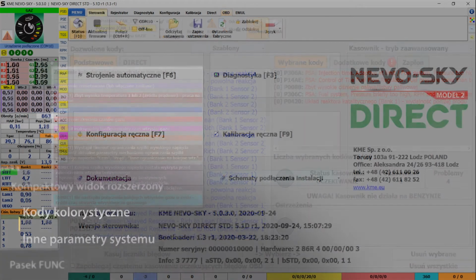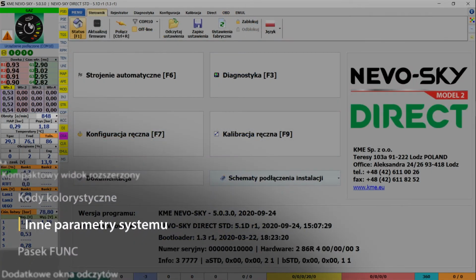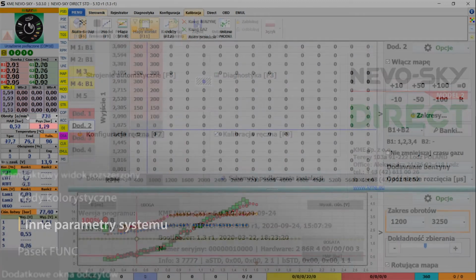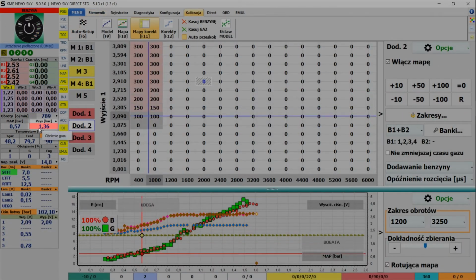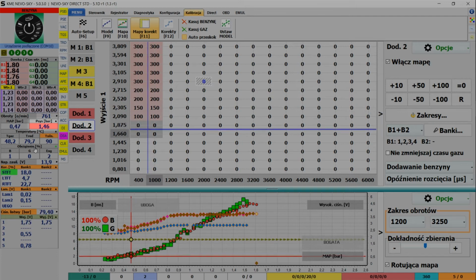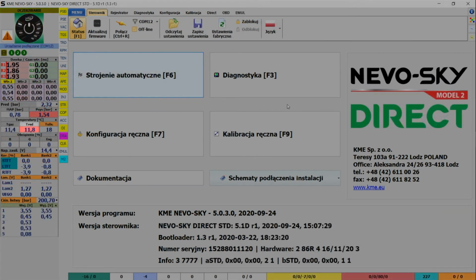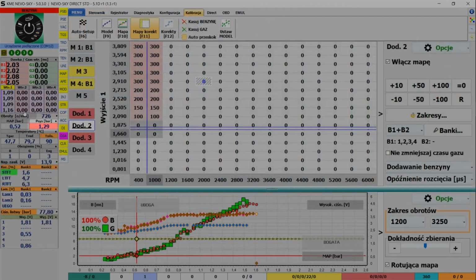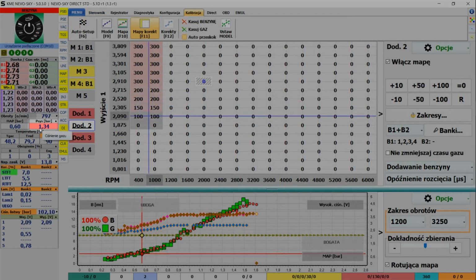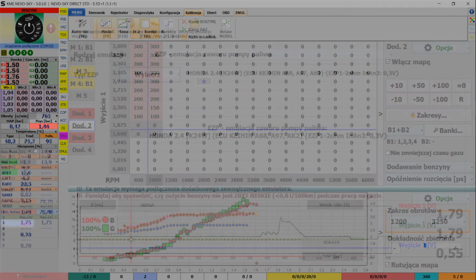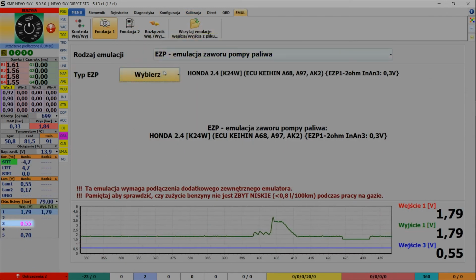Other important parameters of the gas system are displayed below the dose. If any parameter is displayed in red, it means that its value is out of the range appropriate for the system. The olive color warns against approaching such a situation. The reducer temperature is displayed in red when its value is below the switching temperature. On gasoline, the gas pressure value is always displayed in red. Unreliable, suspicious values are displayed in pink. Parameters that are taken from the OBD are marked in orange.